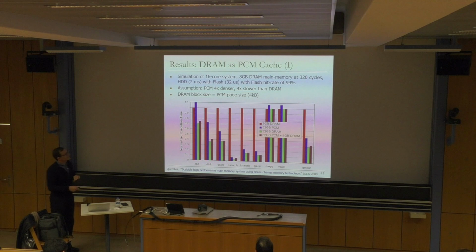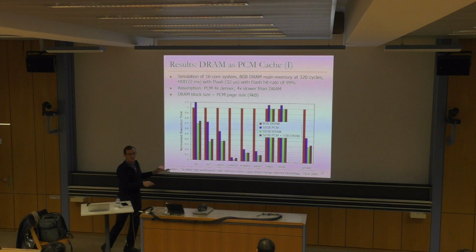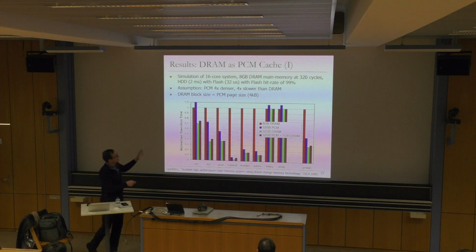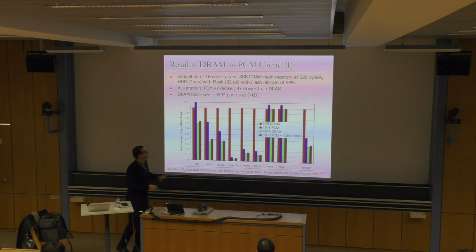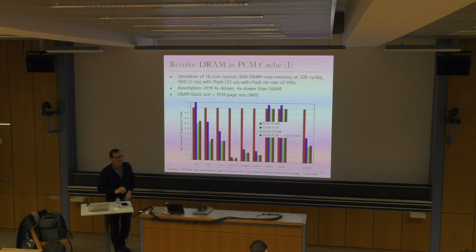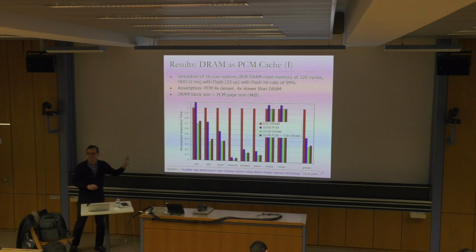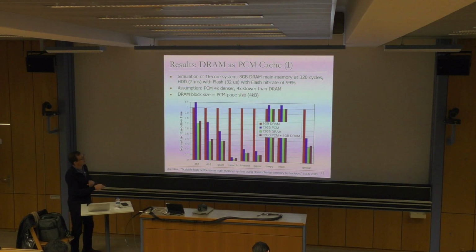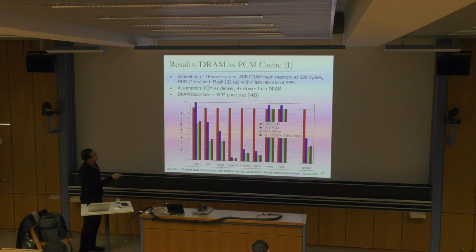Okay, so these techniques actually get rid of a lot of the writes, but they're still not enough, as we will see later on. So this paper takes a more system-level approach because its assumption is that the capacity of phase change memory is going to be much larger than DRAM. So we're going to compare an 8 gigabyte DRAM to a 32 gigabyte PCM system. Basically, the assumption is that phase change memory is 4x denser and 4x slower. Reads and writes, there's no distinction in this work. I think writes are actually more problematic than 4x, we assume that it's more like 12x, right? And I believe that an order of magnitude is a good ballpark today. I don't think writes are going to be as close to 4x going into the future in PCM unless someone solves this very high temperature problem. So the results are therefore a little bit more optimistic here because of that. But also some of the benefits, as you will see, are going to come from the capacity benefits of main memory. There's some simulation that looks at the overall system, and the assumption is that page size is 4 kilobytes.